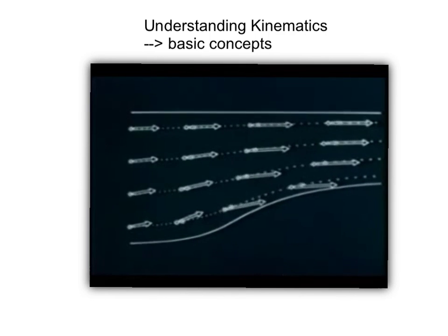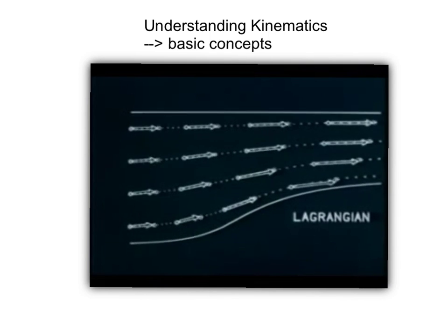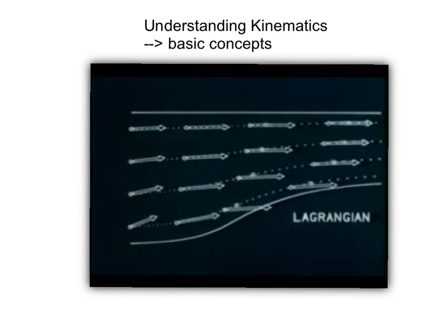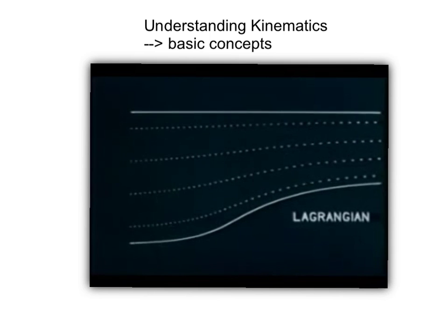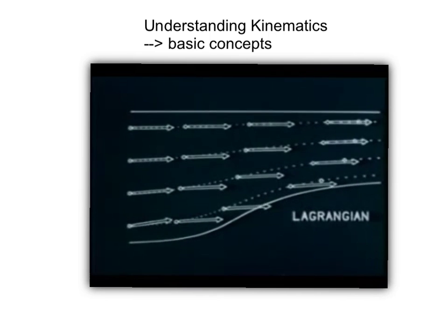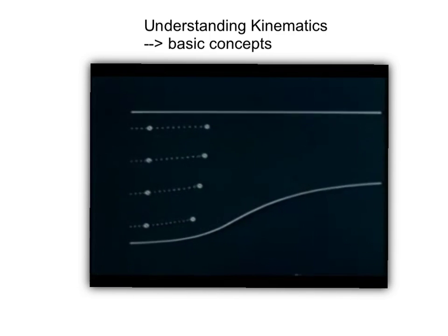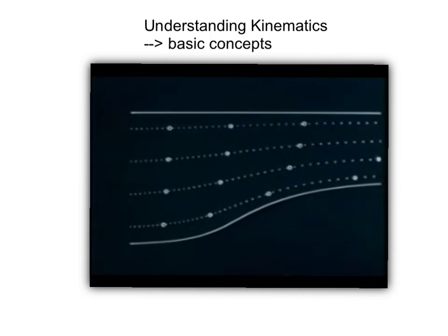This description, in terms of material points, is called a Lagrangian description of the flow. Such coordinates are called Lagrangian, or sometimes material coordinates. From the Lagrangian velocity field, we can easily calculate the Lagrangian displacement and acceleration field. We can imagine attaching an instrument, like a pressure gauge, to a moving point, to make what we might call a Lagrangian measurement.